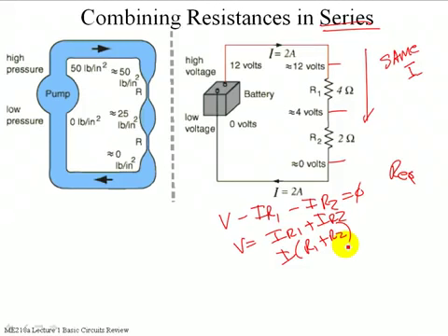Now, people want to do this a lot. They calculate I need a 1.05 kilo ohm resistor or a 1.05 mega ohm resistor. And so they say, oh, I'm going to put a 1 mega ohm resistor in series with a 5 kilo ohm resistor. Does that make sense? Yes? No? I see lots of heads shaking up and down. I'll give you a hint. No.